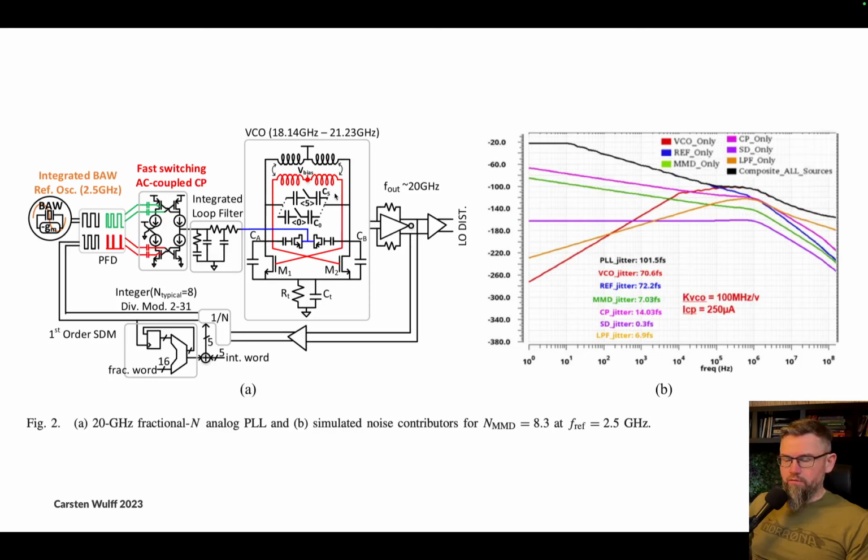So in this case, most often you'll have your resonance tank, which is the combination of inductors and a set of fixed capacitors to get it roughly right. And then you have a tuning part where you finally adjust the frequency by very small adjustments to the capacitance. And here it's just using the fact that the voltage bias across an NMOS or a PMOS for that matter changes the capacitance. And then we have a huge buffer driving a 20 gigahertz output and so on.